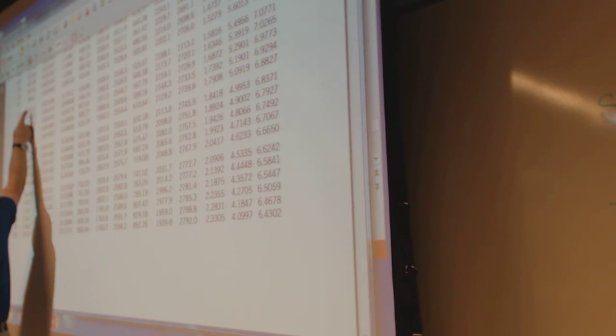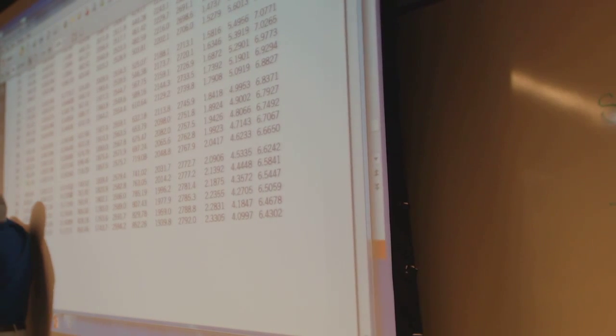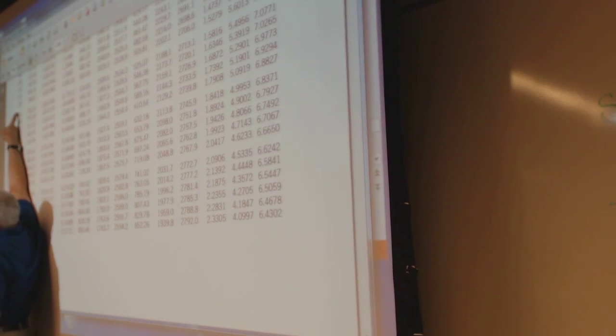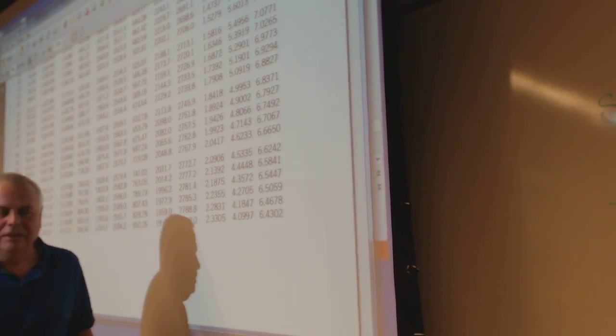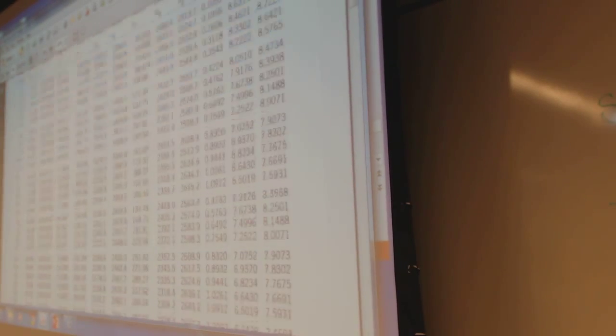Or to look at it another way, at 200 kilopascals, we only need 120 degrees for saturation, which means if we look at the pressure and that temperature, we're above that temperature. So we must be in the superheat table. Probably the best way is to look at pressures and see what the temperature is and see if your temperature is above, below, or equal to that.